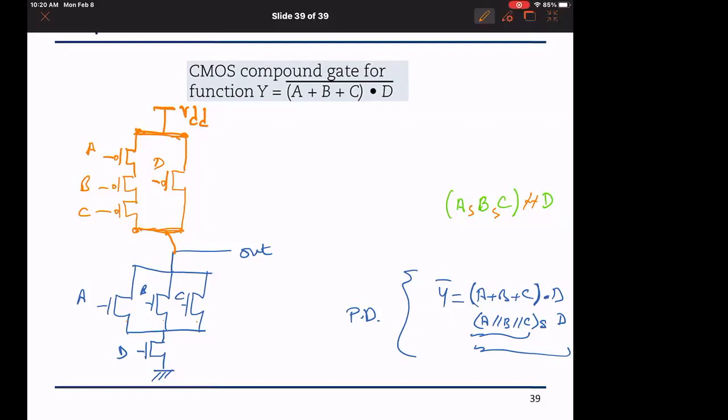You should be comfortable a little bit with the logic functionality. Yes, Hassan. Is there a way to optimize a design in which you use fewer transistors to have the same result? This is mapping your function, the behavioral level. Typically, later towards the end of the course, we will learn that representing a function in terms of NAND gates is the most efficient in terms of what they call logical effort, because they tend to have the minimum penalty in terms of delay. And we will discuss this towards the end of the course.